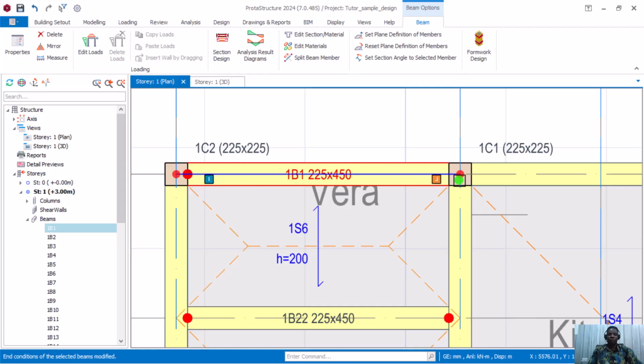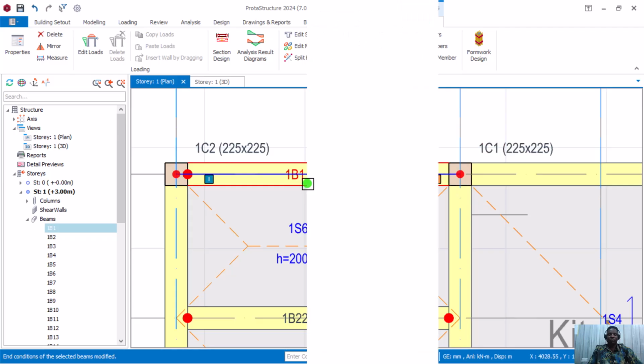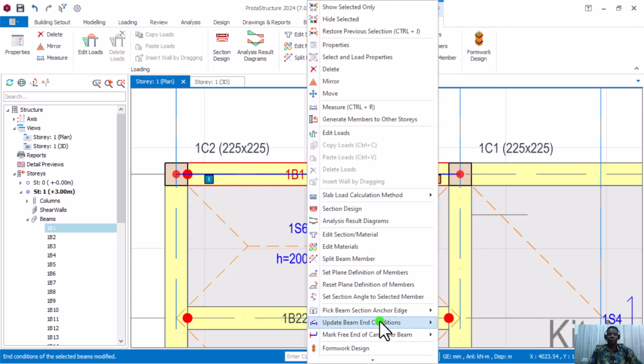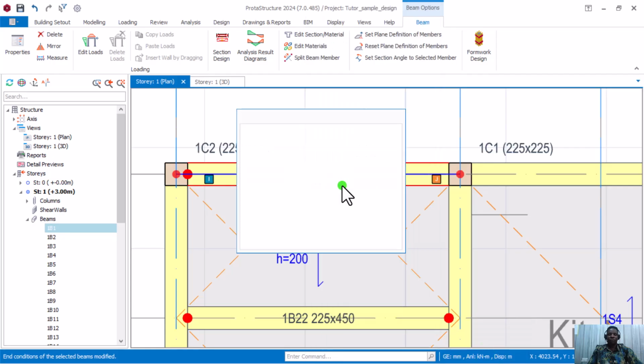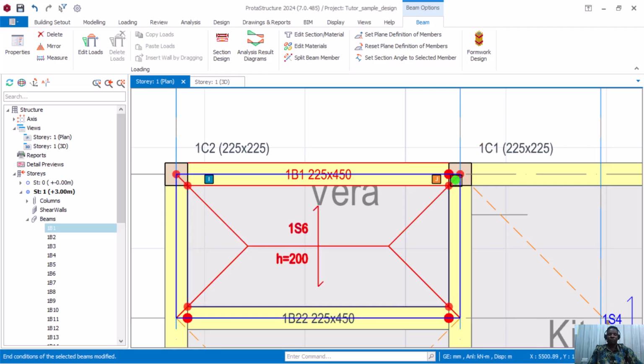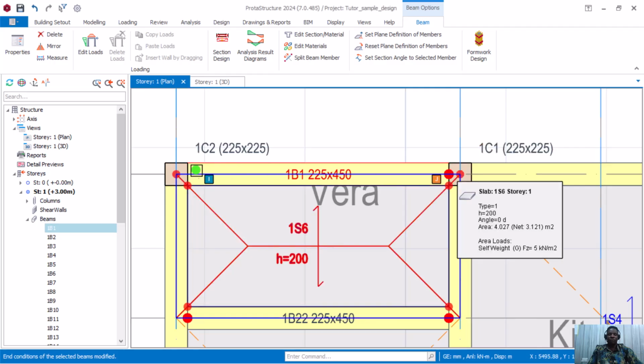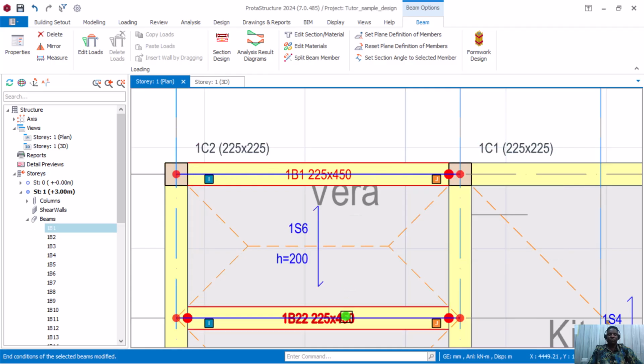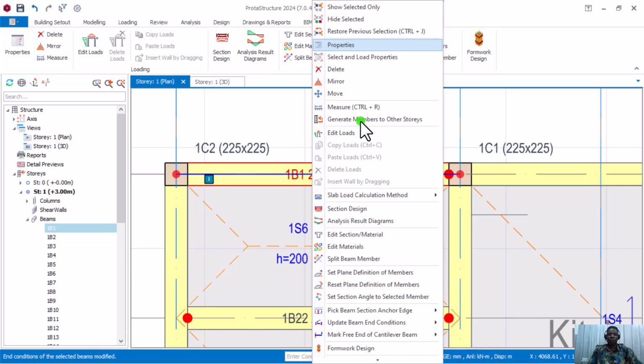If I want to hinge a J, it's going to turn. If I come here and I hinge J, and if I go back and click on J, you can see that the hinge is going to leave the I and transfer down to J. So for you to hinge two beams, you're going to click on both and hinge both end conditions. Okay. So if you hinge only one, it's going to move in that direction, to hinge the particular direction in which you want to hinge.